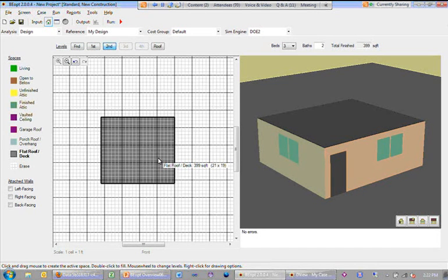Under those circumstances, because we only do either a gable or a hip roof in terms of pitched roofs or a completely flat roof, I would recommend calculating offline an appropriate R value based on that change in thickness and inputting that as a characteristic for say attic insulation or flat roof insulation.